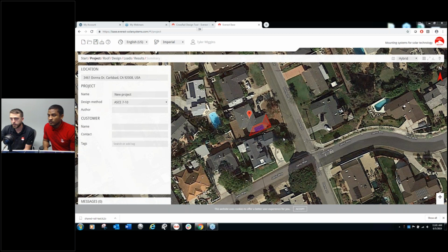Often I have standing seam metal roofs, commercial products. We use third-party attachments with a crossrail. Perfect. You do have that. So with this system, you can do standing seam. I don't think I have time to go over a full standing seam project right now, but you can put in the parameters for what the standing seam widths are. It will still calculate what the allowable spans could be.